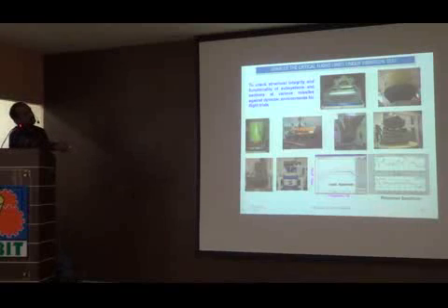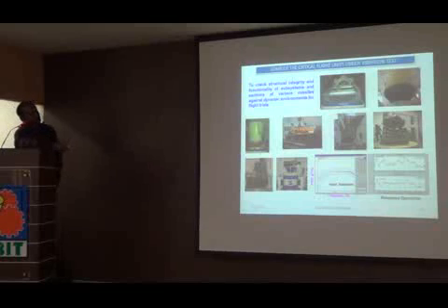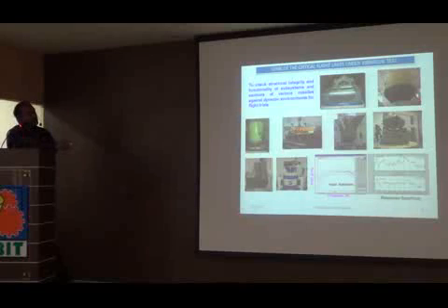So when we give this kind of input at the base, there are some critical elements or critical subsystems inside, meaning packages. At all packages we mount some kind of sensors called accelerometers, and we take the feedback, meaning for this input how the subsystems are responding. See, we have some kind of response like this. If this response is harming this subsystem, we have to modify the structure or the interfaces and rework. If it is not harming, then we will go ahead with this.